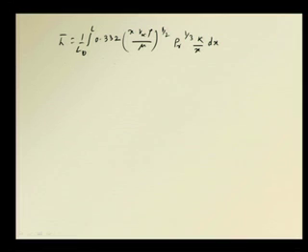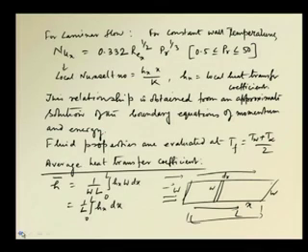So, hx by K is equal to this. If we go back previously, you will see that hx will be represented by 0.332 Reynolds x to the power half, Prandtl to the power 1/3, and then hx will be equal to this, also with a k by x.